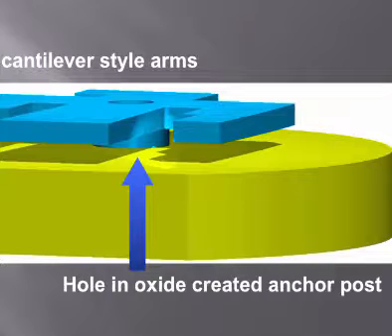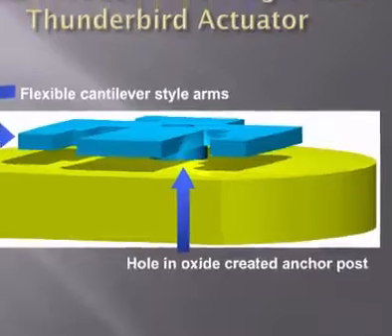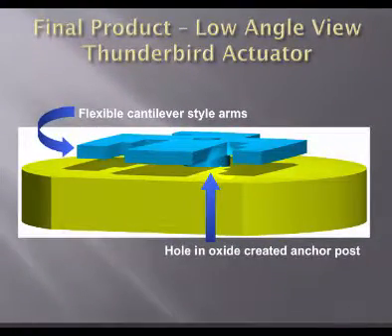Well, that's the silicon dioxide that gets etched away, and that's done with liquid. It's a diffusion process. Now, if this is really as big as we drew it, we'd have to put release holes in here, right? Polycrystalline silicon is the structural layer. Yes, the polycrystalline silicon is the structural layer, and the silicon dioxide is the sacrificial layer because it gets sacrificed. It's the scaffold.